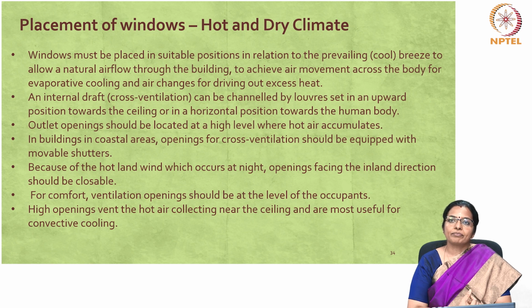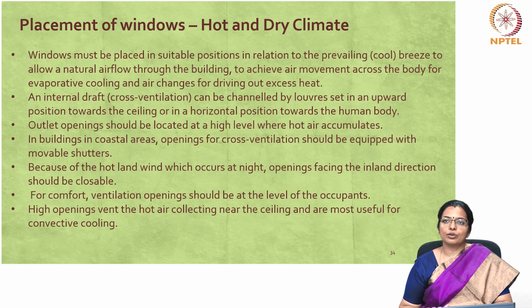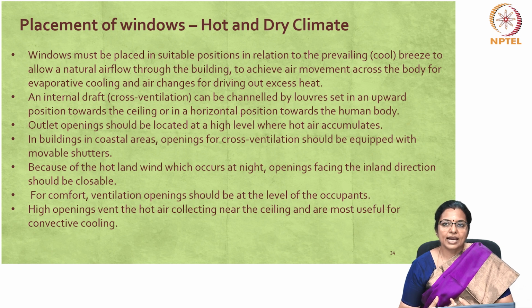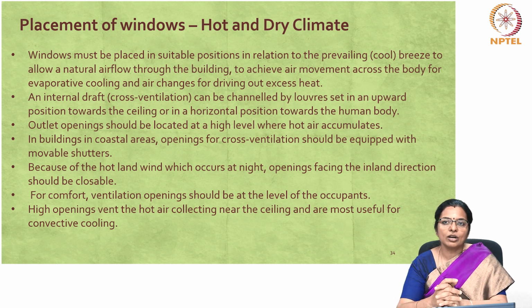Let us look at how windows should be placed. Windows should be placed in suitable positions in relation to the prevailing breeze, which should be cool, to allow a natural airflow to the building, to achieve air movement across the body for evaporative cooling, and air changes for driving out excess heat. An internal draft like cross ventilation can be channelized by louvers which are set upward towards the ceiling or in a horizontal position towards the human body.